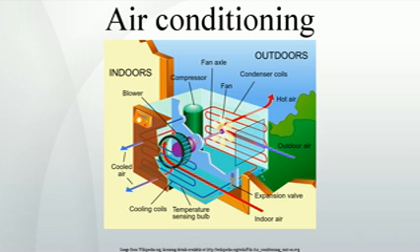As an example, assume that inside the closed system a 100 W heating element is activated, and the air conditioner has a coefficient of performance of 200%. The air conditioner's power consumption will increase by 50 W to compensate for this, thus making the 100 W heating element cost a total of 150 W of power. It is typical for air conditioners to operate at efficiencies of significantly greater than 100%. However, it may be noted that the input electrical energy is of higher thermodynamic quality, lower entropy, than the output thermal energy, heat energy. Air conditioner equipment power in the U.S.